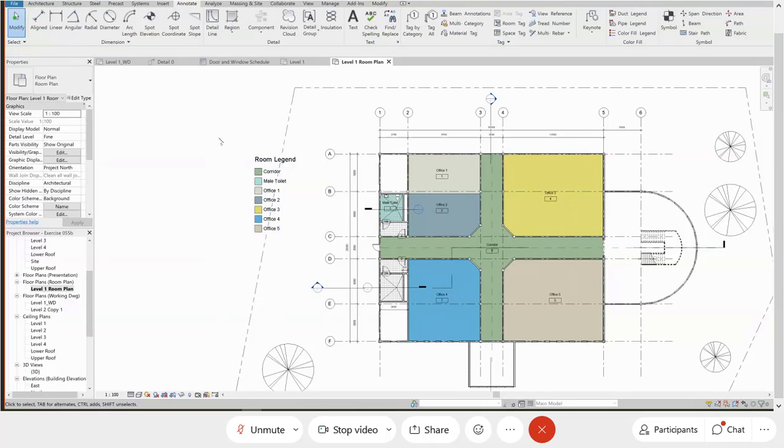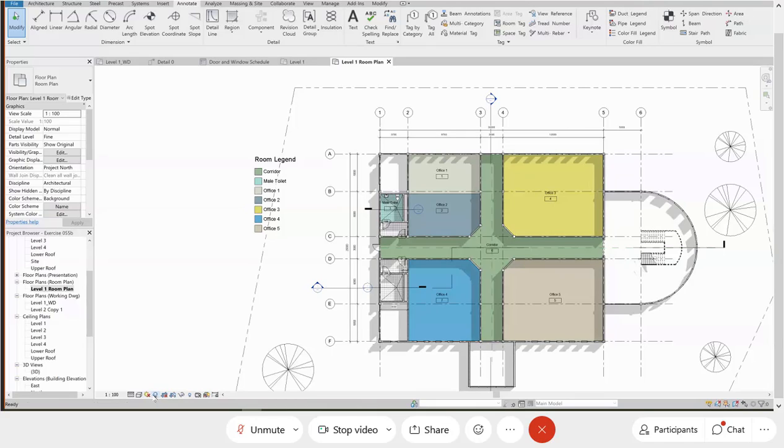All right. Any question? So you can color your floor plan easily within a few seconds actually. And of course when you change the design, you don't need to export your floor plan to Photoshop and color it again and again. Anytime you change, all this coloring will just follow your model. You just need to take some time to set the templates and come up with your hatches, and you can do it quickly.